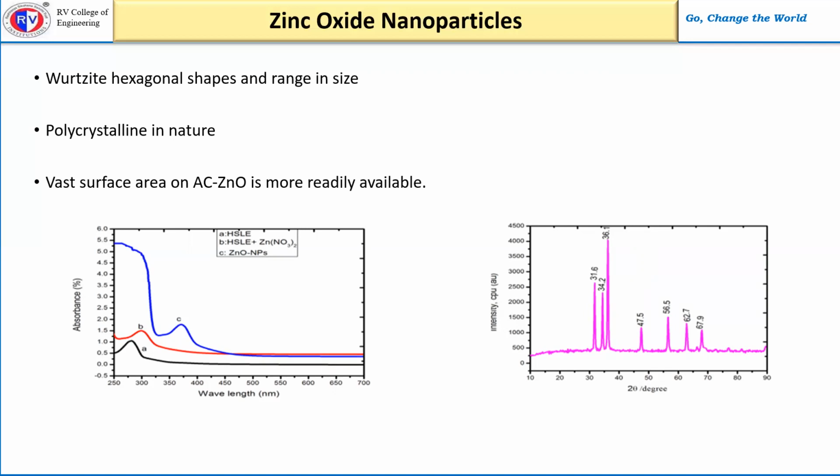10 to 200 nanometers. These nanoparticles aggregate due to their high surface energy from being synthesized in aqueous media, and perhaps due to densification, which causes small spacing between particles. And also, they found that the pattern of rings and spots indicates that the nanoparticles have a bigger grain size and a more uniform shape. And also, they are polycrystalline in nature.